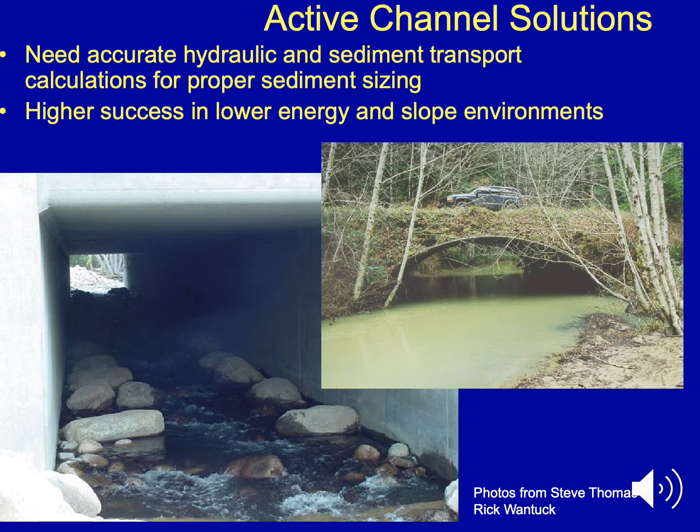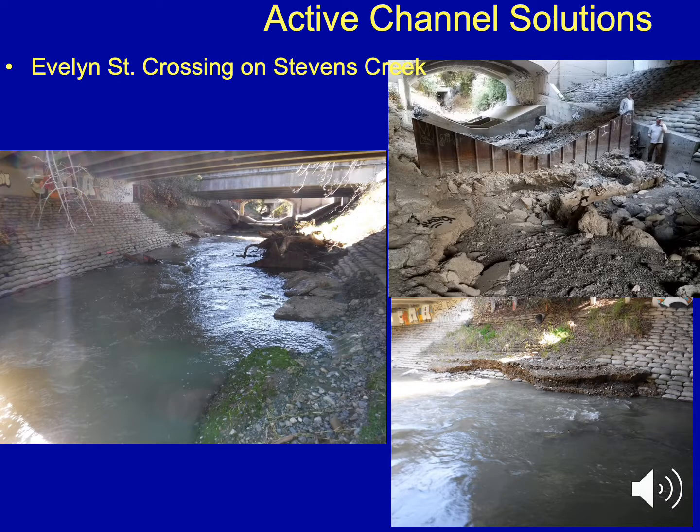crossing. And I actually don't know if this arch here is a stream simulation or active channel width, but you get the picture of the kind of environment where these tend to work better. Here we're at close to bankfull flow, relatively mild energy happening within there. And in a system like this that may have been small gravel, you put in large cobble into small boulders, they tend to stay.